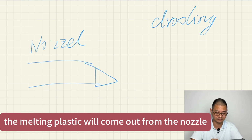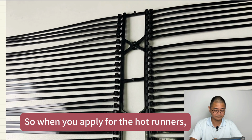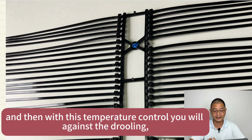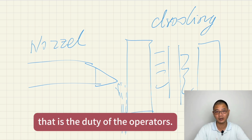The melting plastic will come out from the nozzle. So when you apply the hot runner, the injection point has temperature control. With this temperature control, you can prevent the drooling, but you need to set a good temperature. That is the duty of the operators.